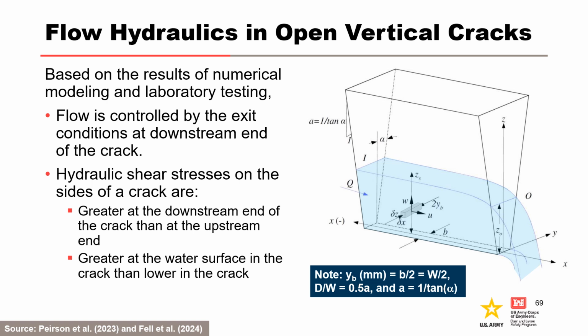As erosion occurs, the downstream end of the crack widens and the water surface in that part of the crack lowers. The new control becomes the non-eroded crack just upstream of the eroded part. This process will progress upstream and not cease unless the crack closes by swell at the upstream end, filters arrest erosion, or there is a drop in headwater.